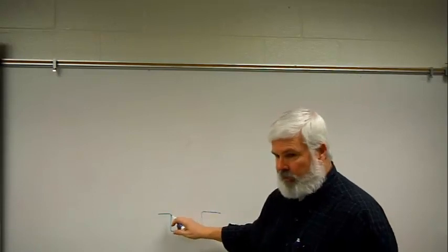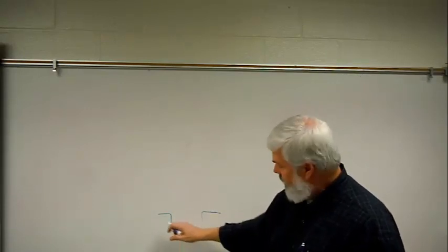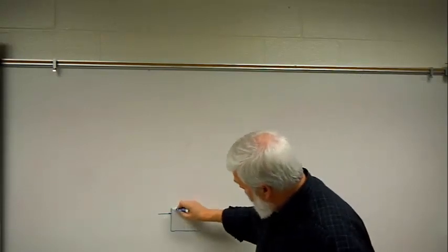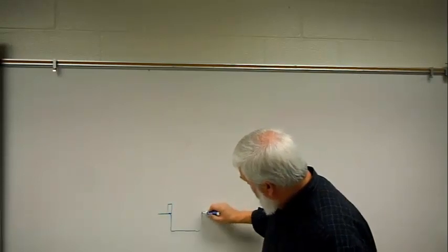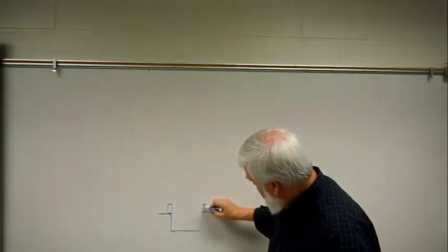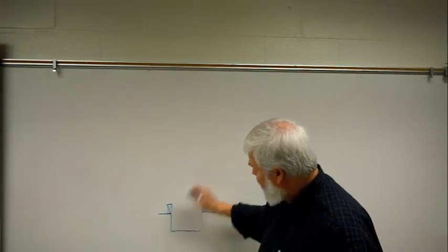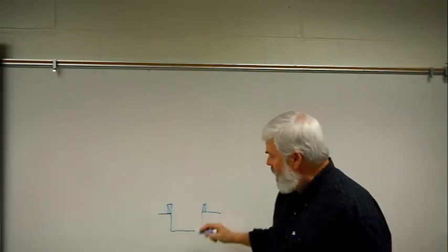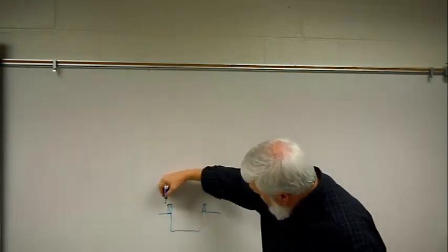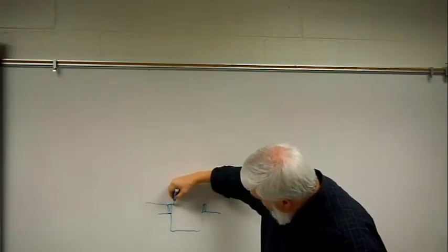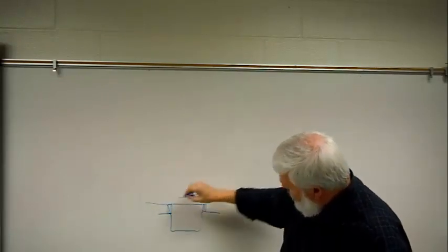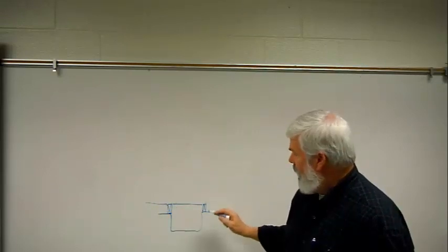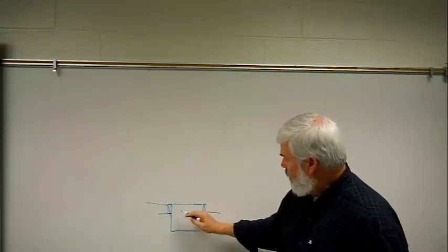But usually you dig down about 8 inches in the ground, and then when you form it up to be able to pour your footings, you put some 2x4s here, which gives you another 3.5 inches, we'll call it 4, so that you can dig a footing. You pour a footing now in this trough and fill it with concrete,